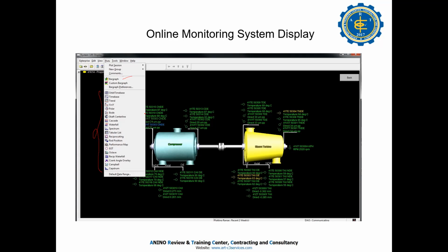So we have to monitor the vibration. If the vibration goes up, then we have to monitor it daily or weekly. If the temperature gets high, that's the problem. But if the temperature is steady, then we keep monitoring until such time the vibration goes down. That's the importance of trending.